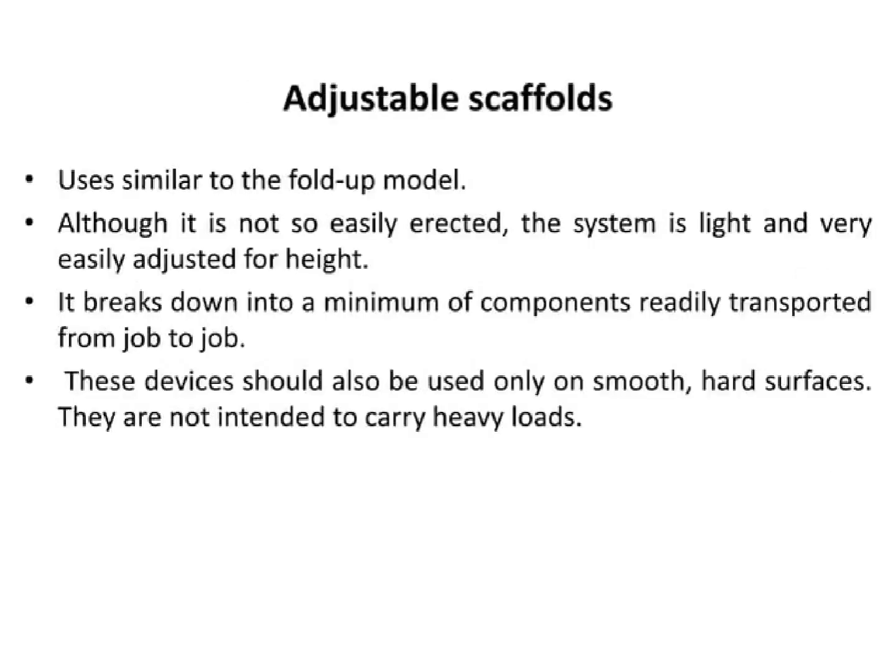Adjustable scaffolds are light and easy to transport and adjust for height, making them suitable for similar purposes as fold-up scaffolds, although more effort is required for erection. It is important to note that these are not designed to handle heavy loads, and should only be applied on hard, smooth surfaces.